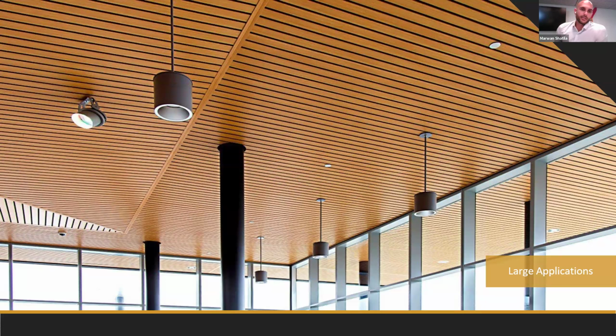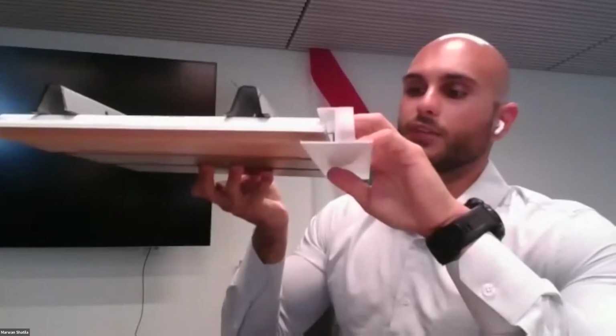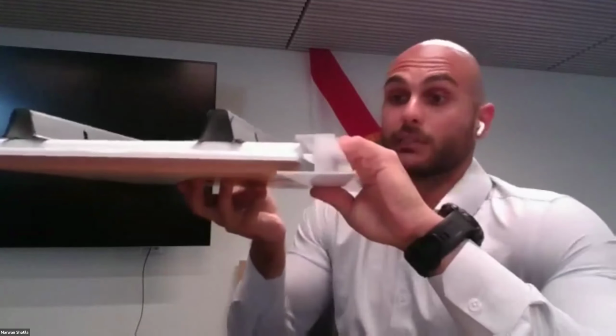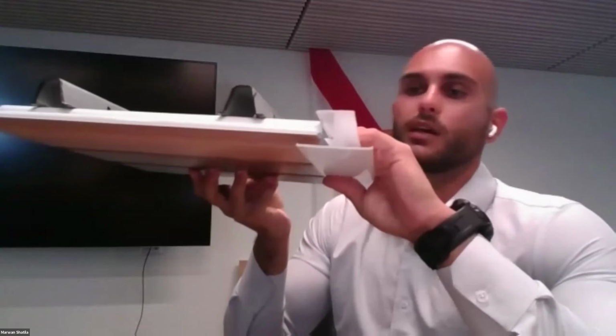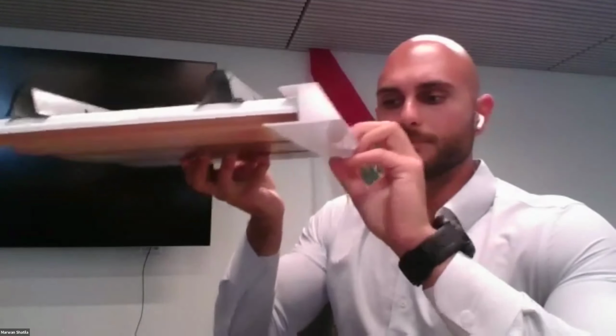One thing that's notable in this photo right here is one aspect that we have to consider whenever we're installing in an exterior application, which is just the use of expansion joints, which I'll show you right here. This expansion joint is simply used to accommodate for the fluctuation in temperature, because all things in buildings themselves will expand and contract. And so it's utilized right here where the butt ends of the panels join into it.